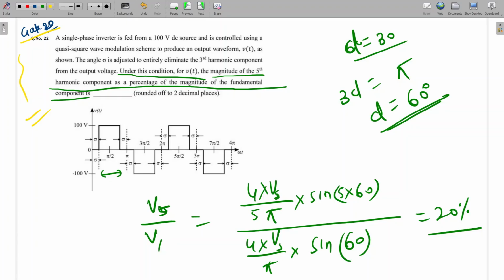Sir, in each case, we will remove the sine omega t term for VRMS. Yes, RMS means, let's say this is any sinusoidal voltage, Vm sin omega t. This is a sine waveform. So what will be the RMS? RMS will be maximum divided by root 2. Is it clear? So sine omega t is the sinusoidal quantity. Other than that, what is there? It's the peak value. Is it clear? It's the normal phasor concept. That you should do. There only we can make mistakes.